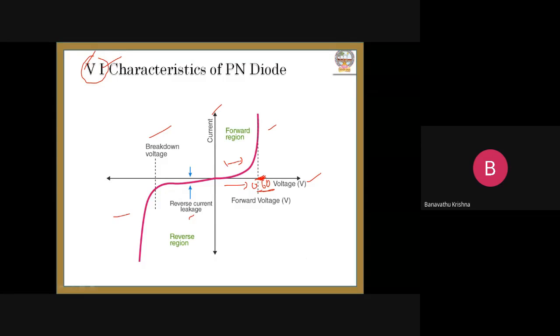On condition. Okay. Coming to the reverse bias condition. Here, in reverse bias condition, the diode acts as reverse biased, and generally there is no current, but there is a current. The current is generated due to minority charge carriers. That current is called the reverse saturation current or leakage current.